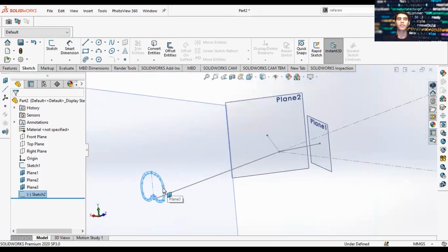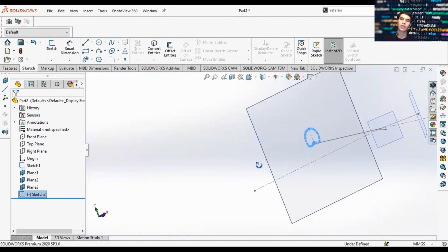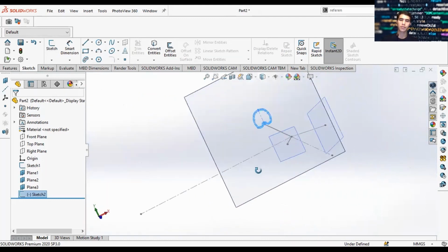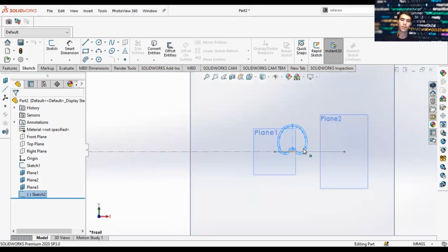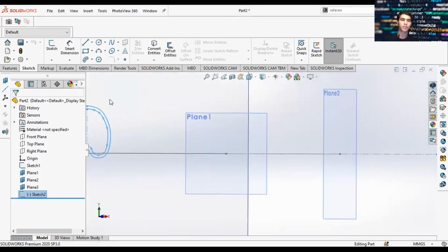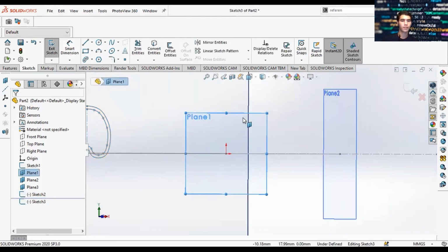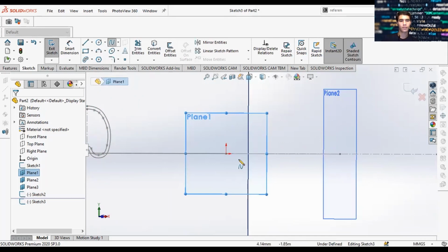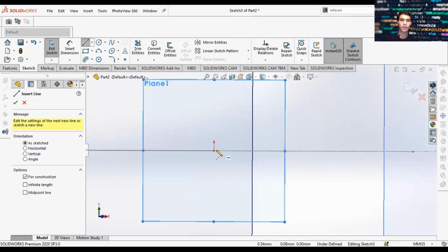So what we have so far, we have our straight sketch, and now we're going to extrude it. Actually, before we extrude it, let's go ahead and finish drawing the other sketches. Same procedure.